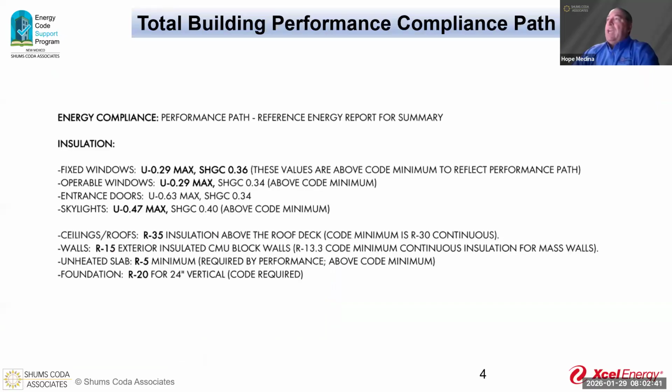So here you can see that we have an excerpt from a set of plans on a title page. And right up front, it tells us our energy compliance, we're using the performance path. It gives us what we have for our insulation values. It tells us what we have going on with the U-factors. This one even goes so far as to tell us what's above code and what's not above code. Very nice. It's a great place to start. As inspectors, we know what's happening.